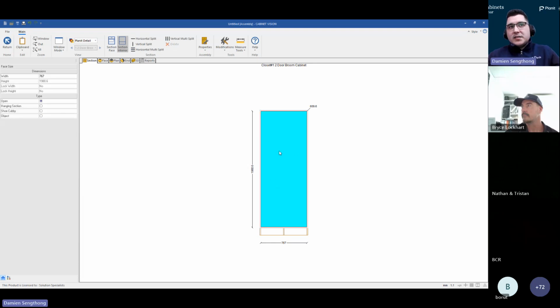It is also easier to assign a hanging rail when using Closets. As you can see, we've selected the section interior. Then on the left-hand side, under types, we do have an option for hanging section. Once you select that, you are presented with other adjustments, such as the reference, as in the horizontal movement of the rail. The top clearance would be from the top of your interior section to the rail. So you are able to adjust this if you need to.